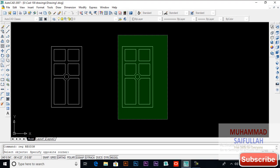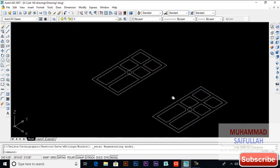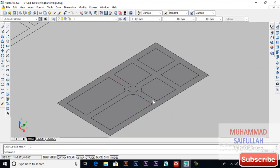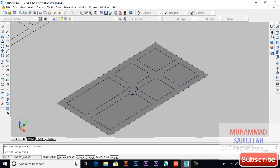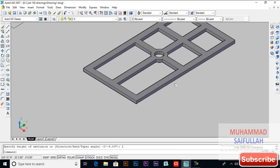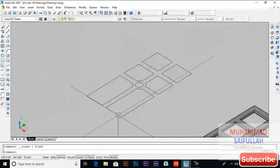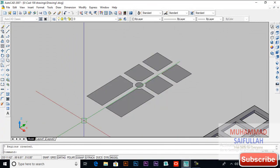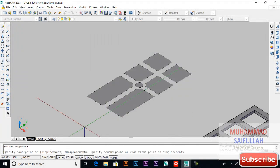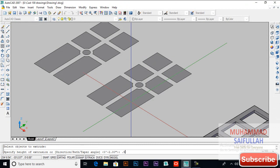Region it, REG for region, and you can see, so you can subtract it from outside, select outside, then enter, then select these inside objects. Now extrude it 2 inches. Now delete these outside objects, region it, copy it, extrude it 0.5 inches.